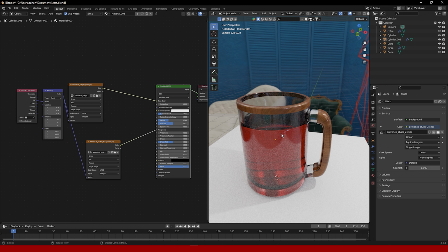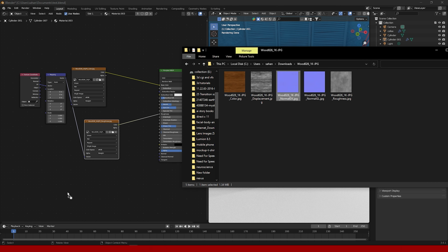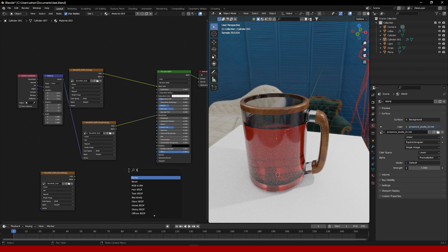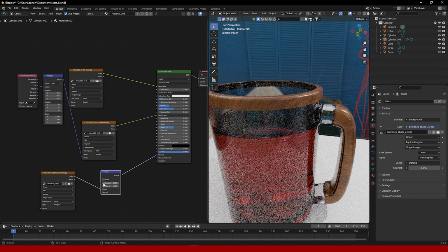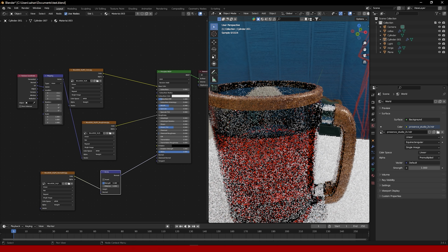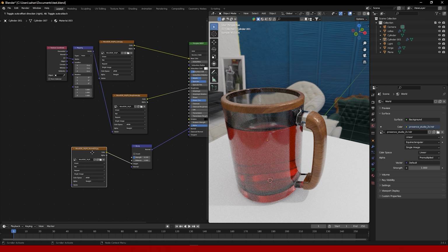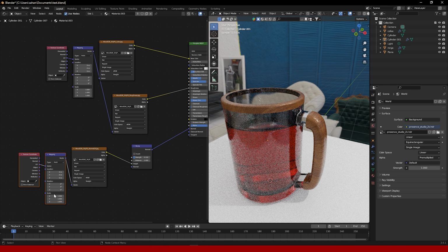I use normal map instead, and I drag this normal map into our shader editor. Now I'm gonna search bump map to get a little bumping effect, and I plug height value to our image texture, and I plug this output to normal map, and you can see it has a little bumpy effect, and we can change this value to change our bump height. And I press Ctrl T to get texture coordinate and mapping node, and it can change scale, and I set scale to 5. So now you can see it's more detailed.